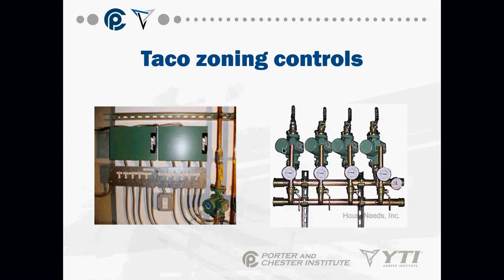Usually a telltale sign that you have a lot of air in a hydronic heating system is that it actually sounds like water traveling through a brook. You'll literally hear it. You'll hear a lot of vibration in the pipes and stuff like that. Usually if a boiler has no air in it, you really won't hear too much noise coming from your radiators and your baseboard and stuff like that.